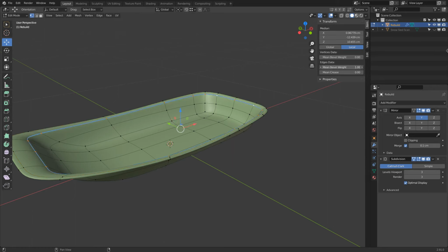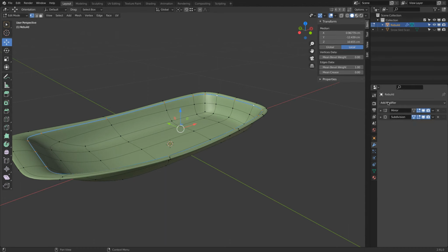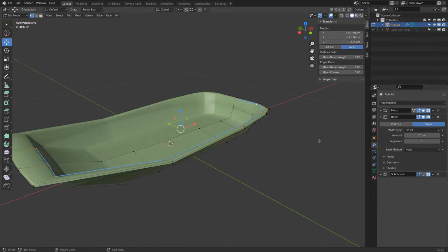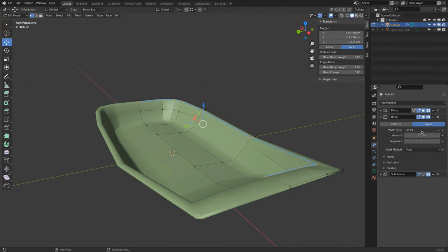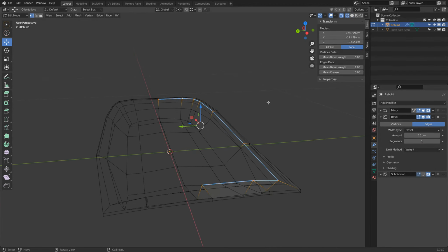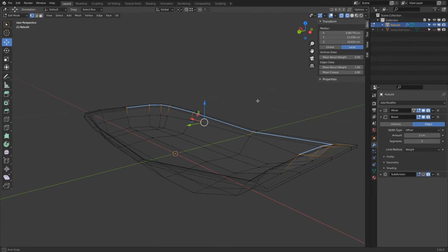This we will select first, and we give this a bevel of 1. Then we can go add a bevel modifier, and we move this in front of the sub D modifier. We will set limit to vertex, so only the edges selected will be rounded. 10 centimeters is a lot, maybe a centimeter, and maximum of 3. We don't really need more edges.